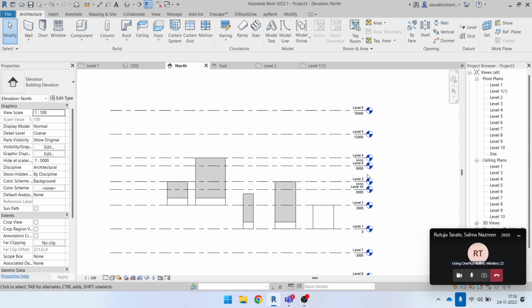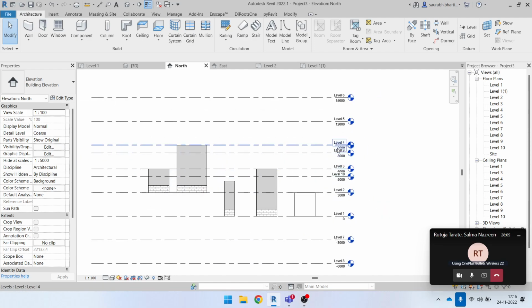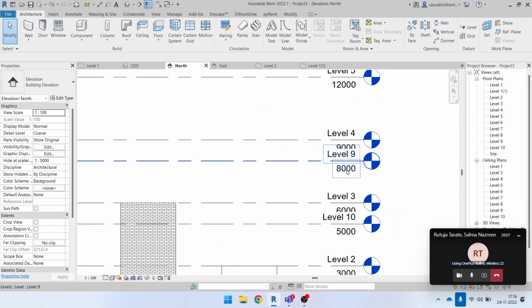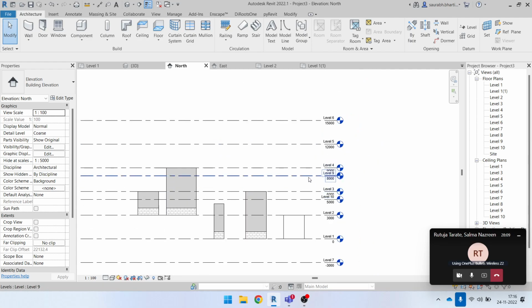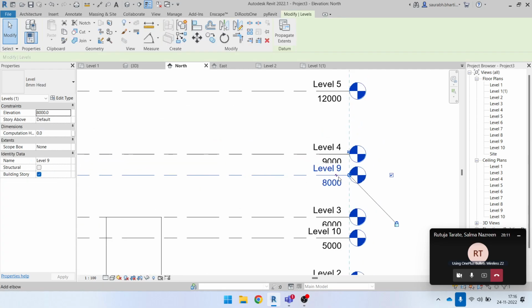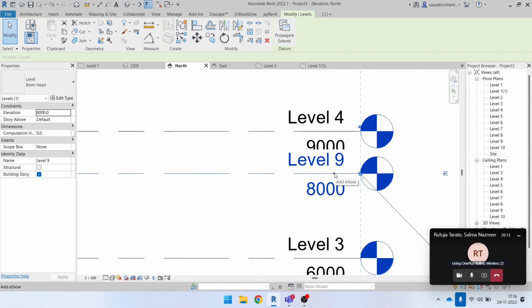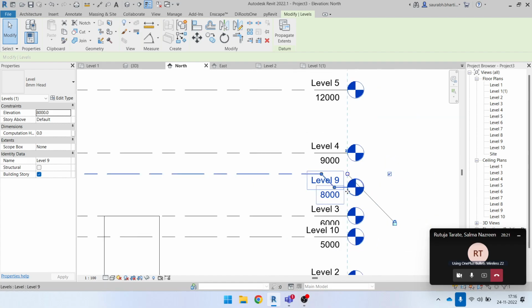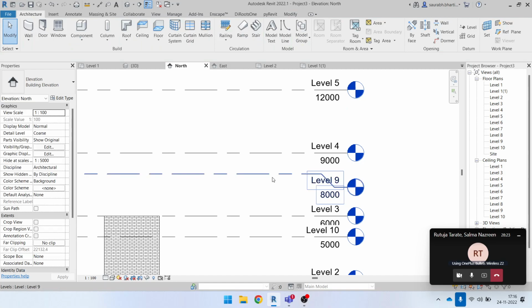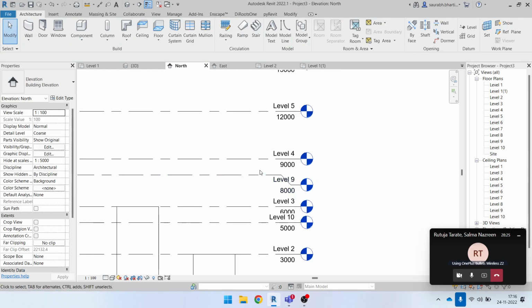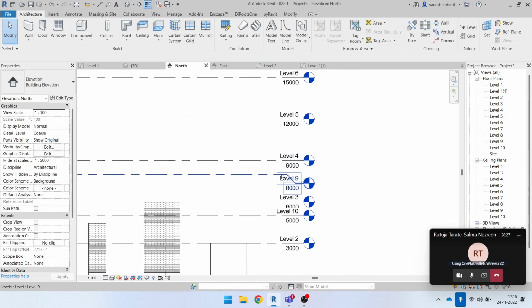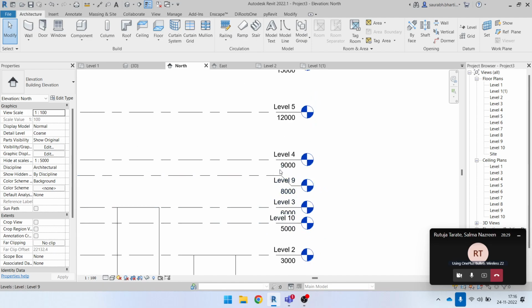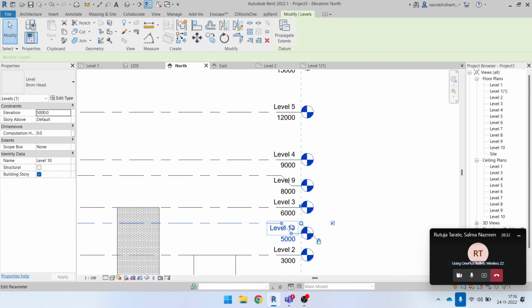Now you can see there are many labels, and this view is hiding underneath this one. So what you can do is just click here and you will get this crooked view. You will just add an elbow here. Whenever you go to this place, it will give you an elbow option. You can just click on it, and now you will see your level will come down something like this, but your level will be at the same place, only the name of it will be a little bit shifted with an elbow, so that all the views would look fine.